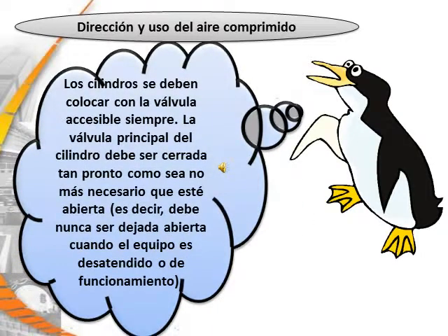Cylinders should be placed with the valve accessible at all times. The main cylinder valves should be closed as soon as it is no longer necessary that they be open. They should never be left open when the equipment is unattended or not operating.